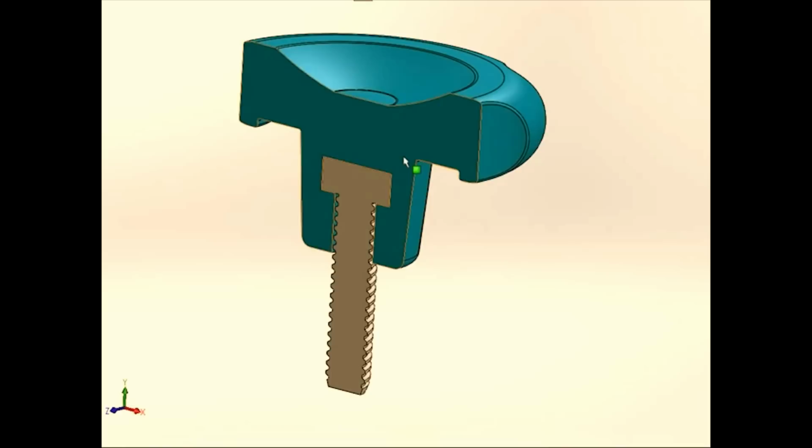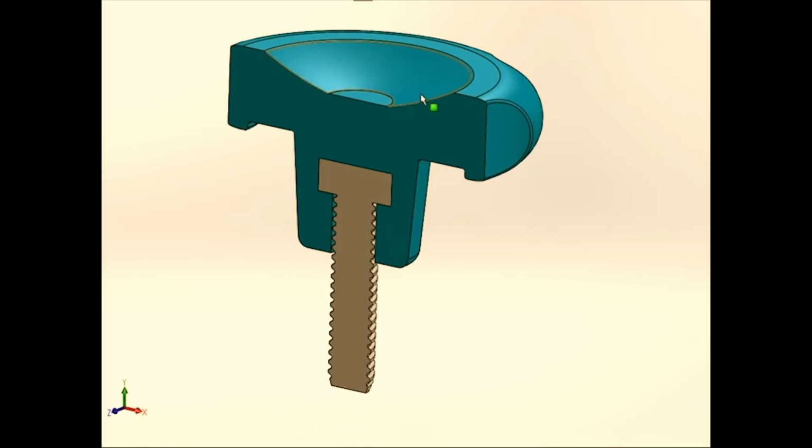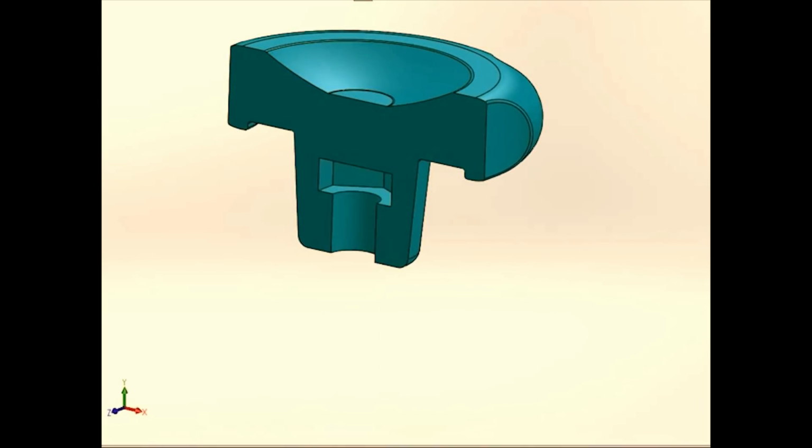So I have my bolt here. What we want to do, if I was to open just my handle in Insight and put it in there in this orientation, we've got to think about how it's going to be inserted into the model down through like that when we're going to put a pause in there. So some other things that we're going to have to do is we're going to have to elevate the model off the table so it has room for that bolt to stick out of it, and we're going to have to modify the support so that it's taller and it allows a hole here to accept the bolt.